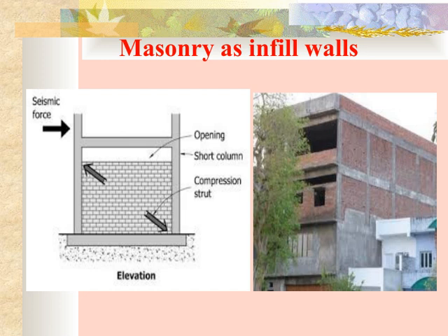However, it's important to remember that they are non-structural, meaning they don't carry the load of the building but work together with the structural frame. This makes their placement and connection details crucial to prevent issues like cracking or instability. Connecting these infill walls properly to the main structure ensures they perform their role effectively while maintaining the integrity of the entire building. So, understanding how masonry works as infill is essential for designing safe, durable, and efficient buildings.